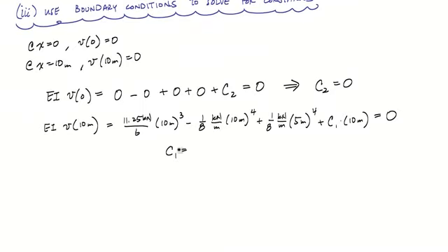And so C1 here, when you work out the math, will come out to minus 70.3125 kilonewton meter squared. And here the units are correct, because this C1 is kilonewton meter squared times the length, which gives you kilonewton meter cubed, and EI over here has units of kilonewton meter squared. So when you divide this through, for the displacement you'll end up with units of meters with the way that we have this equation set up.